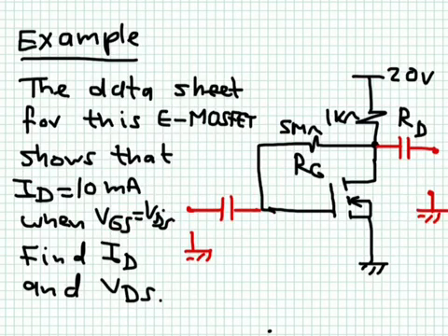So you can use this transistor as an amplifier by connecting a capacitor here and then applying your weak signal between these two terminals here. So you can apply a weak sinusoidal signal here, for example. And then this will cause small fluctuations in the VGS voltage. These small fluctuations will be reflected in large fluctuations in the drain current, and then this will result in an amplified signal at the output port. So you get here a way stronger signal. Here you apply a weak signal, you get a stronger signal at the output, and this is how these devices work as an amplifier.